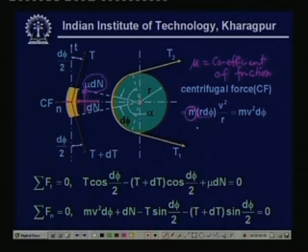This is basically the mass of a belt of unit cross section, that is the belt mass. This is the belt mass for a 1 meter length, suppose. So, this is what we get as m, and r d phi is the length of the belt, giving the total mass of the belt, and v square by r.